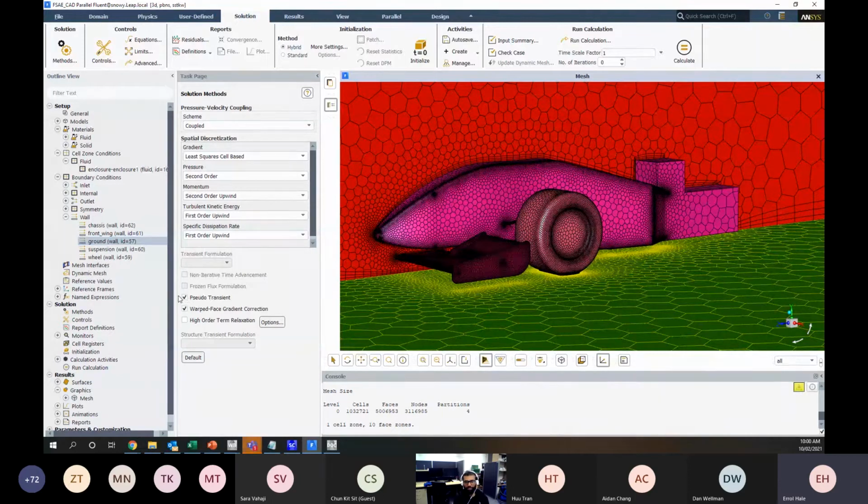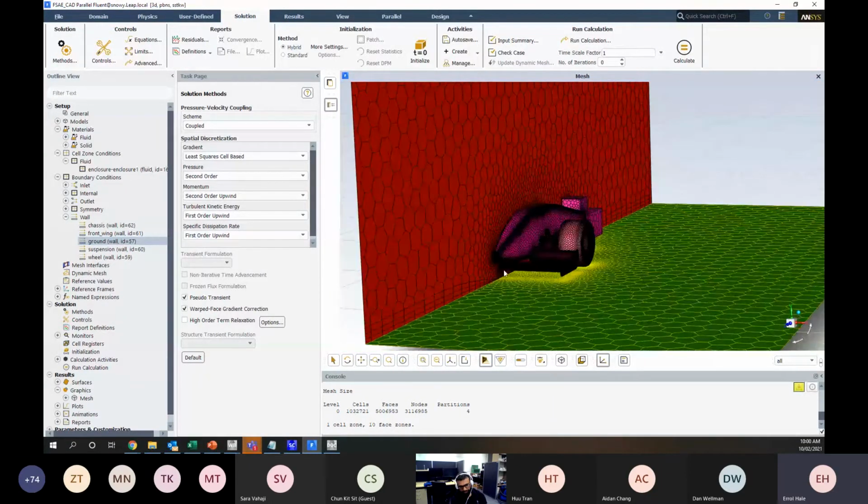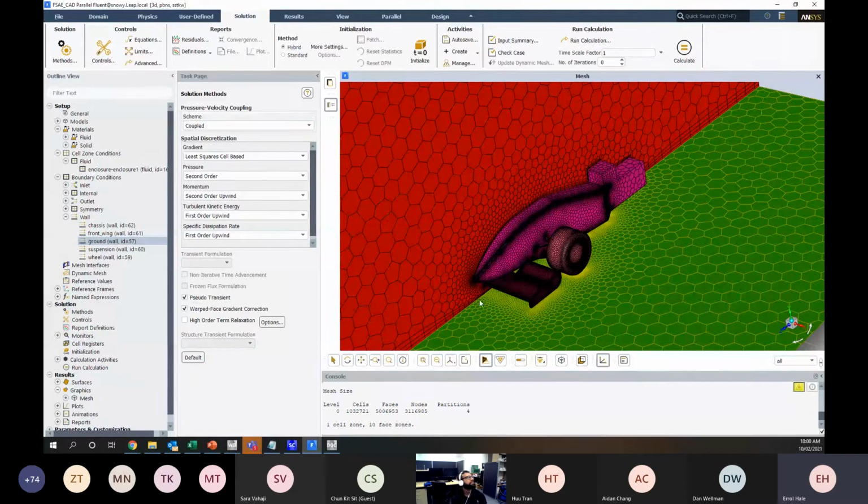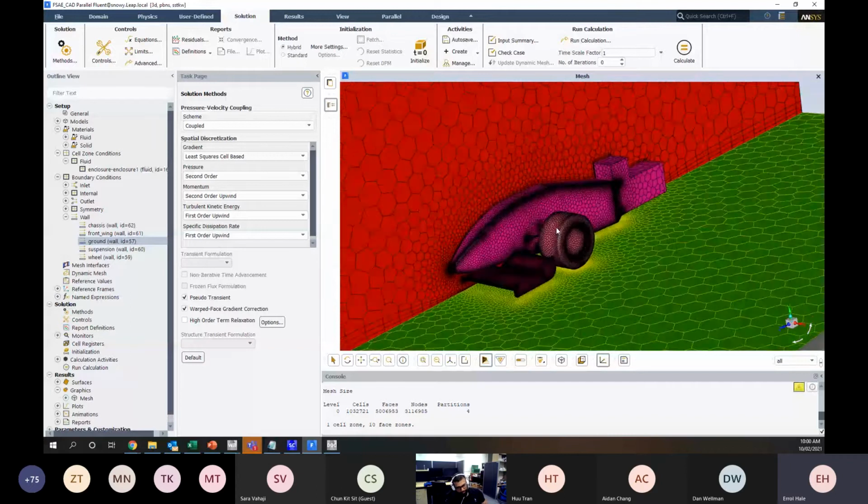So one of the difficulties that we have in CFD generally is that, especially for a case like this and for all cases, fluid dynamics is highly nonlinear and it is highly transient. Okay, so every time we're trying to say run an 11.1 meters per second wind over this vehicle and get a steady state result, we're often not able to get a steady state result exactly because it's not a steady state flow phenomenon.